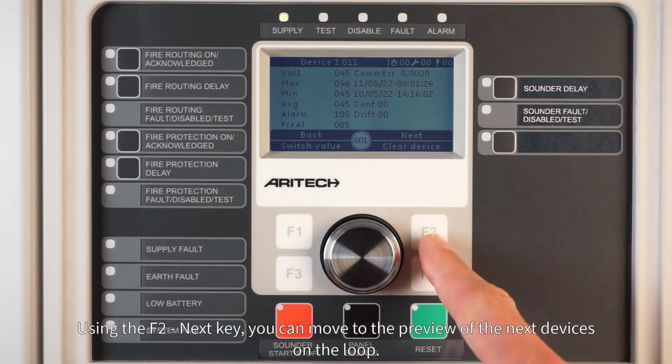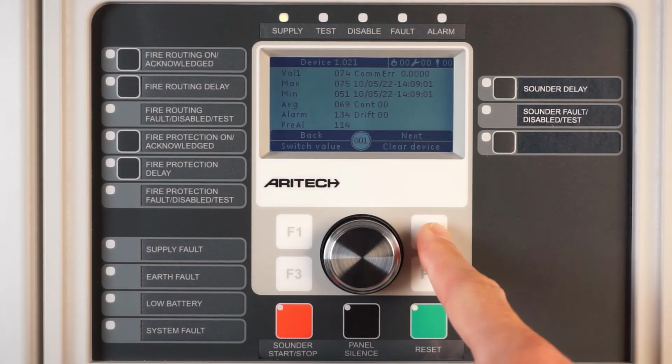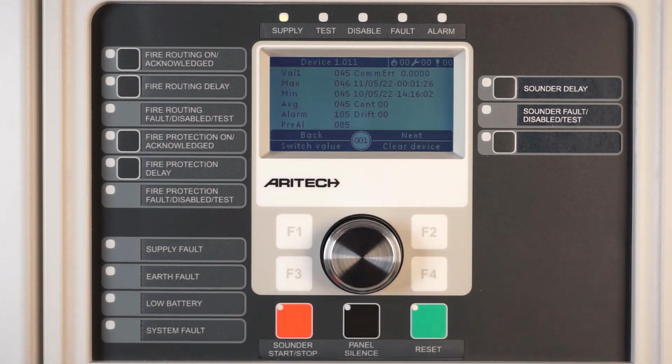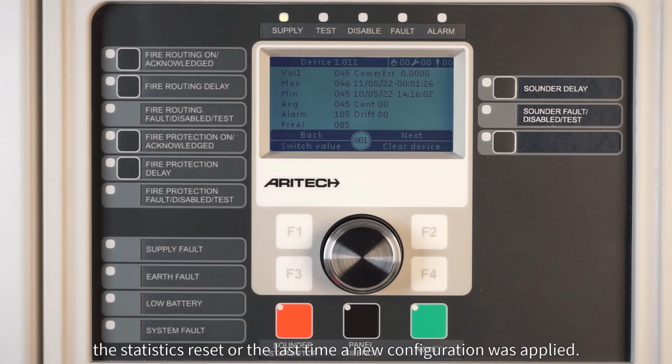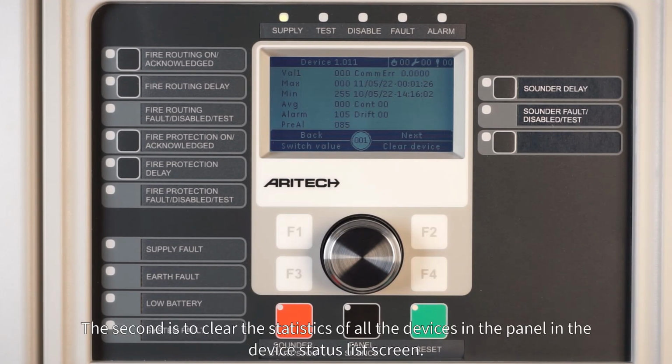Using the F2 next key, you can move to the preview of the next devices on the loop. All the statistics values are processed since the panel reboot, the statistics reset, or the last time a new configuration was applied. In order to reset the statistics, the system allows two options. The first one is to reset the statistics of a particular device using the F4 key. The second is to clear the statistics of all the devices in the panel, in the device status list screen.